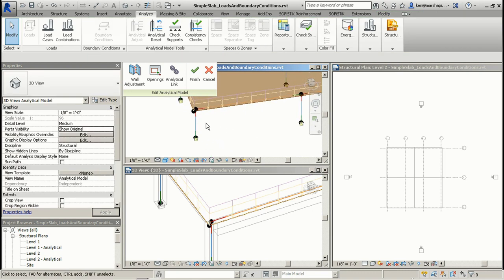And let's see, how many elements? We have beams, columns, and braces that have analytical models, floors, and foundation slabs. There's also an analytical representation of an isolated foundation, but it's one of the ones that I disagreed with. It's a point at this point. So there is analytical model information there for extraction, but it's not already set up for being considered a plate element or that sort of thing.